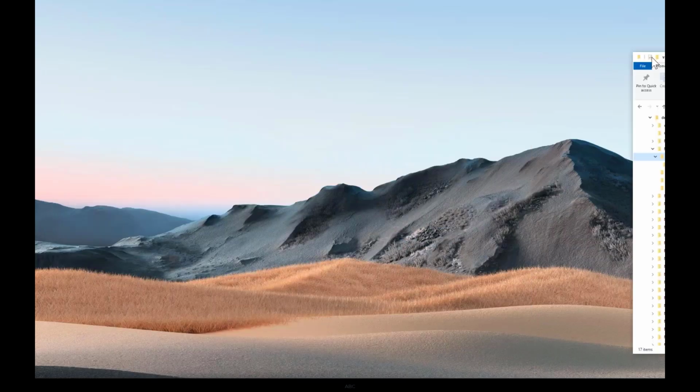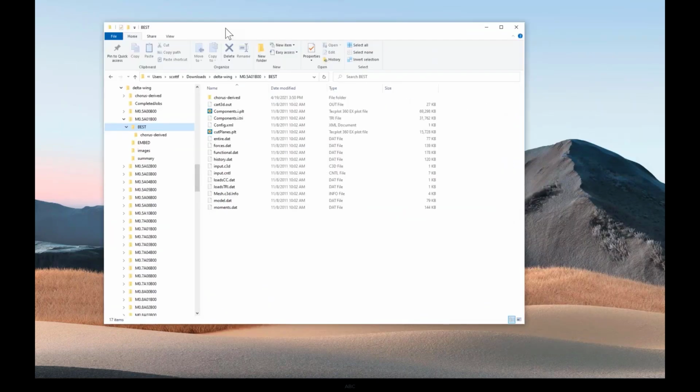So I'll give you a little bit of a lay of the land here. With this Cart3D data set, you can see how the data are organized into folders. Here we have Mach 0.5, Alpha 0, Beta 0, Mach 0.5, Alpha 1, Beta 0, etc., all the way down to Mach 1.8, Alpha 10. So I think this actually totals 99 individual runs.